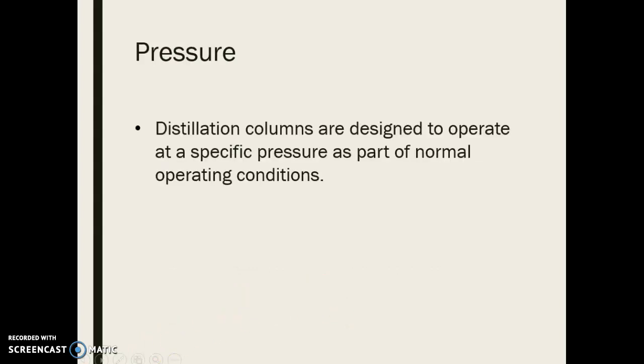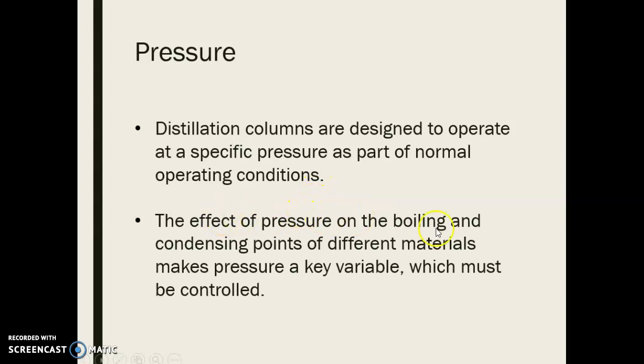Okay, pressure. Distillation columns are designed to operate at a specific pressure. That again affects the temperature. The effect of the pressure on the boiling and condensing points always makes the pressure very key, and you have to control that carefully.